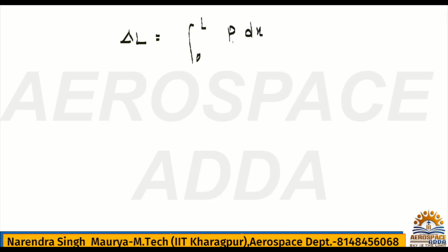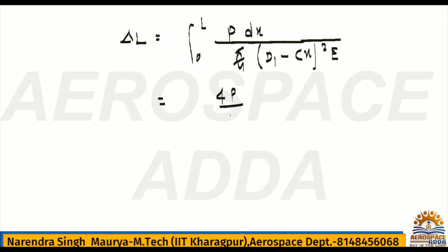Tx you can write as area, pi by 4 d1 minus cx whole square, into Young modulus E. Now just simplify this. So what you will get is nothing but 4P divided by pi. You can take outside the integral 0 to L, and pi E, Young modulus, also take. What you will get is dx divided by d1 minus cx whole square. This value you will get inside the bracket.